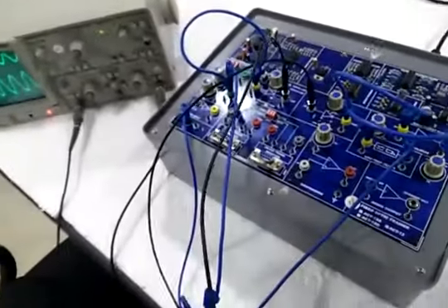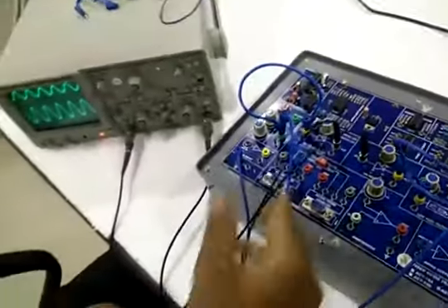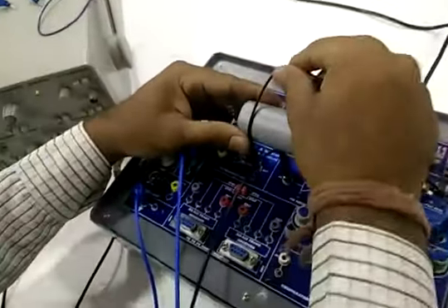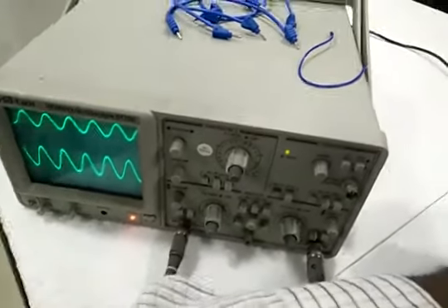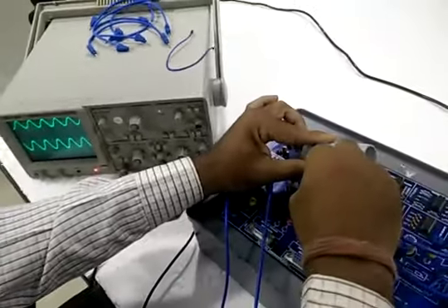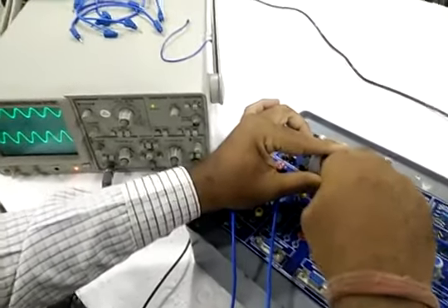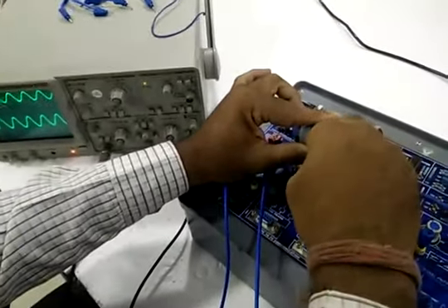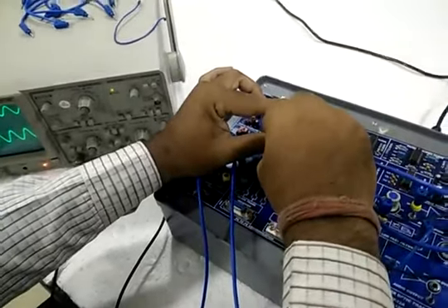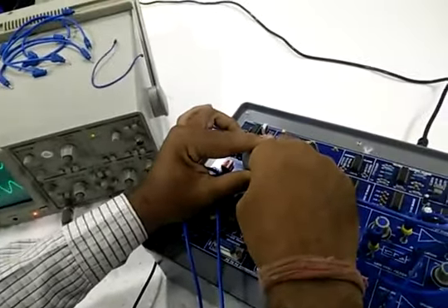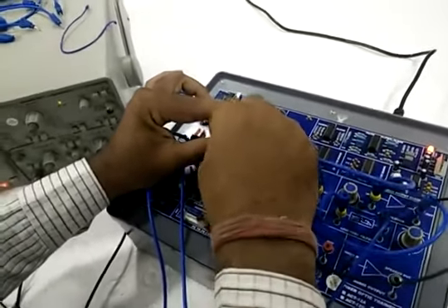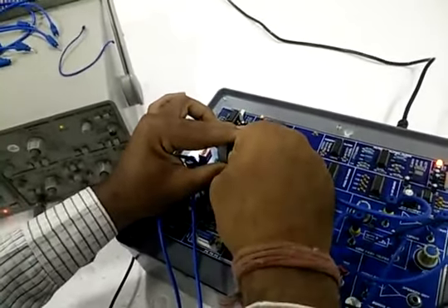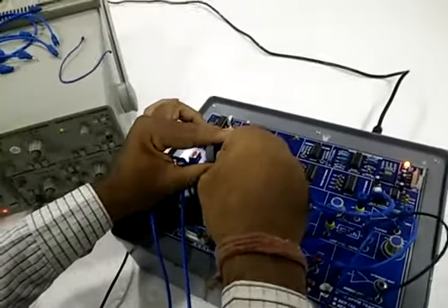Now apply a bend to the fiber optic cable with the help of the mandrel provided, and we can see that the amplitude is decreasing. Now measure the output voltage after applying the bend. We can see from the value of output we have obtained that when we apply the bend, the output voltage decreases. Thus we have studied the bending loss experiment.